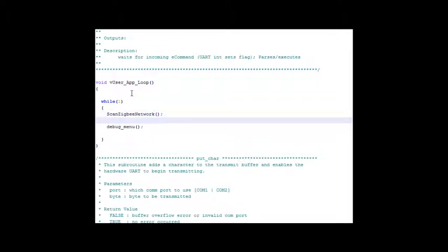Your code will execute once per cycle of this loop. Also, the debug menu function will be entered each cycle. If Hyper Serial Port has sent no characters to the MSP430, it returns after checking the serial port. This only takes a few instructions.